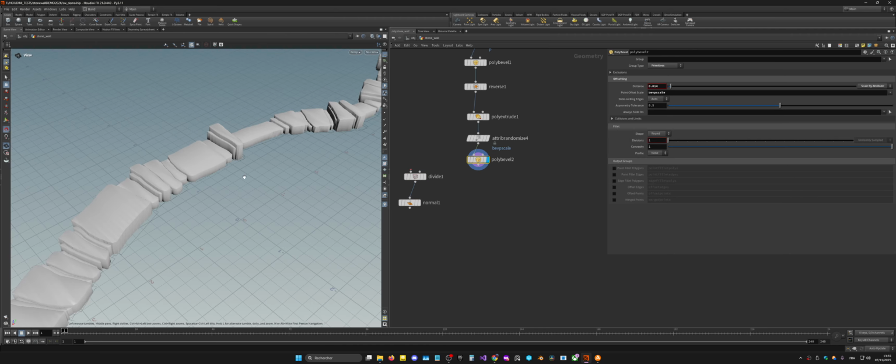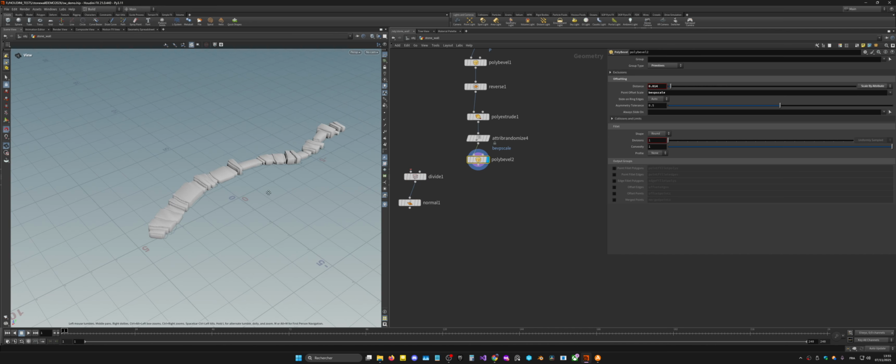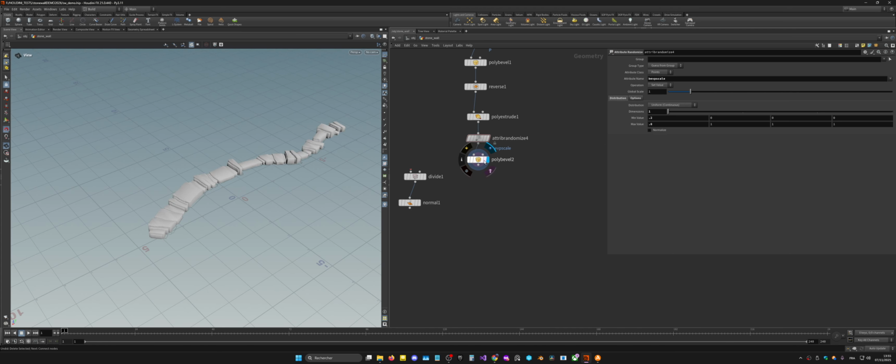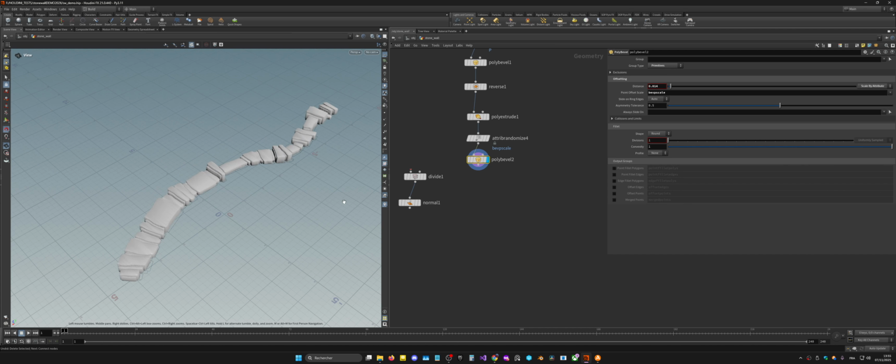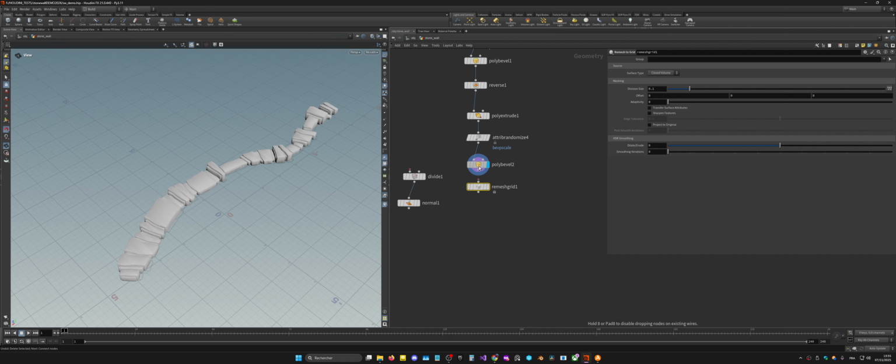I just finished my extrude, oops, sorry. No. My extrude and my bevel, so everything is closed. That is important because now I will voxelize it with Voxelize Labs Voxel Mesh. That is a remesh grid, a very useful tool that is converting to VDB, then converting back to polygon, and you can choose the resolution.